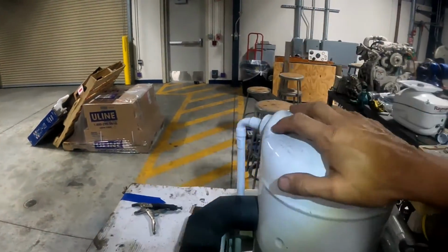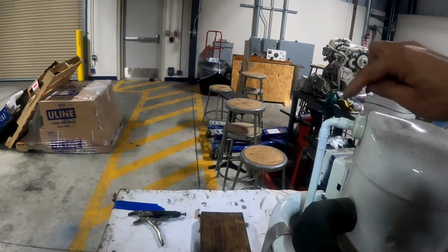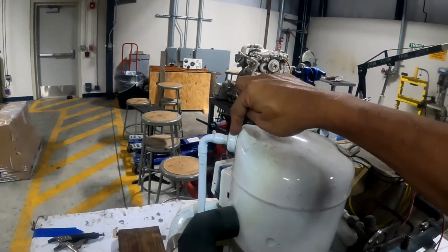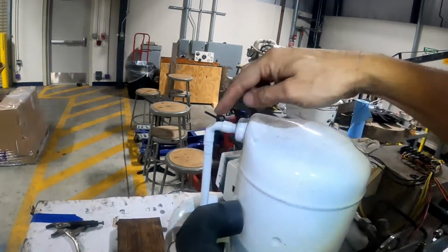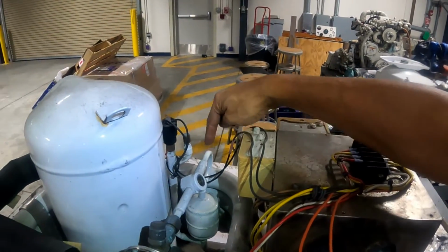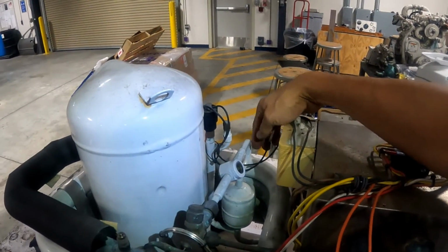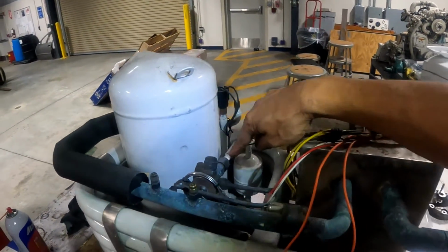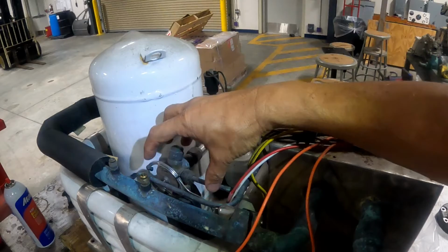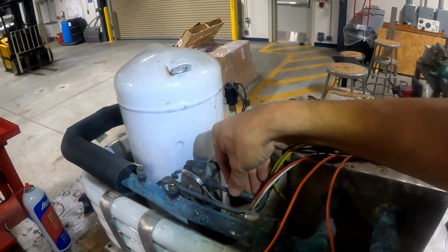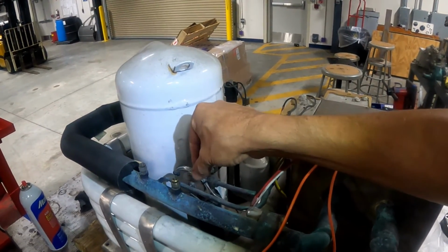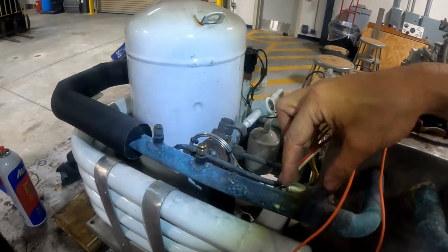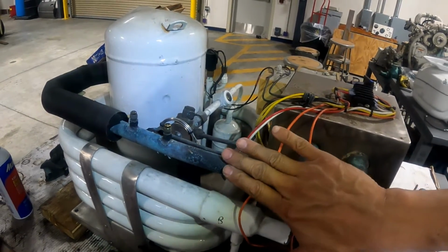This is the compressor, high pressure at this point, high pressure and high temperature, supersaturated vapor. The supersaturated vapor goes down and enters into the accumulator, and in the accumulator right now it is liquid, high pressure and high temperature. This is the thermal expansion valve. The thermal expansion valve receives the signal from this capillary pipe, and this capillary pipe is connected with a bulb, and the bulb is touching this pipe.